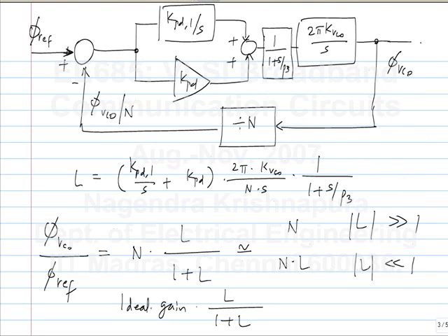Okay, next, let's say the VCO has a phase error. The output of the VCO is the ideal phase of the VCO plus some error. What is the transfer function from that phi error to phi VCO? Let me not even call it phi VCO, let me call it phi out. What is the transfer function between phi error and phi out? Qualitatively, what will it be? High pass, low pass, band pass? High pass.